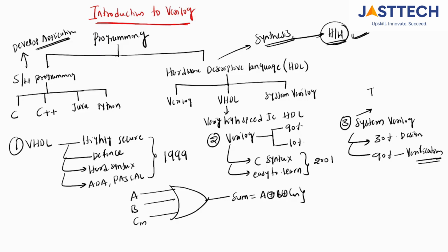But if you want to write verification for I2C separately, you write a test bench only for that. If you want to write a test bench for UART, you need to write it separately. There is no standardized test bench, so that's why you go for UVM. UVM is Universal Verification Methodology.